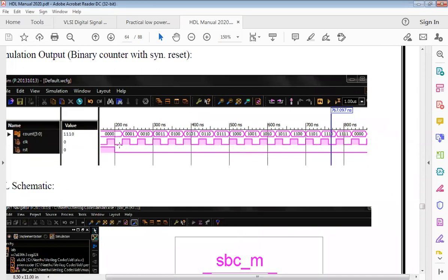Okay, fine. So this is your clock here going high, low, high, low, high, and low, right? So it is just going on and on. So reset, okay, reset here, whenever it goes from high to low, and this should be in rising edge. This should be in rising edge, and a reset should not be high. So in that case, the count will move to the next value.